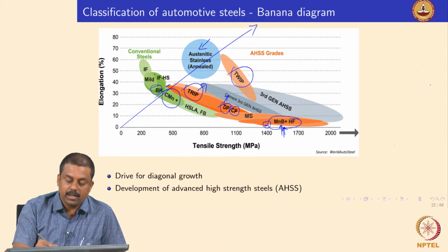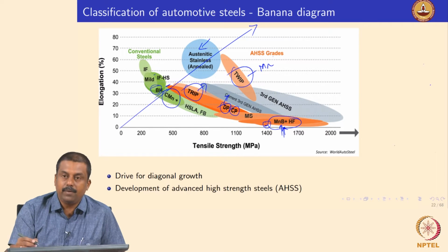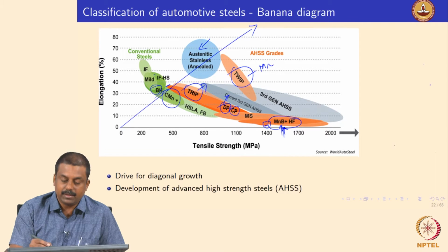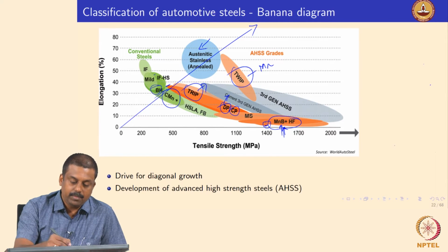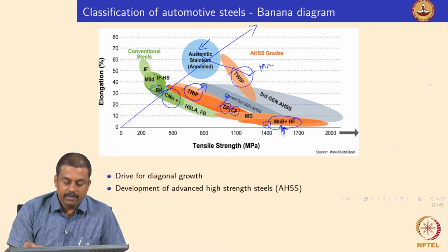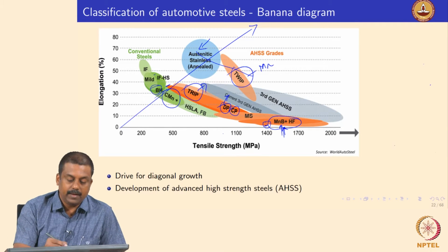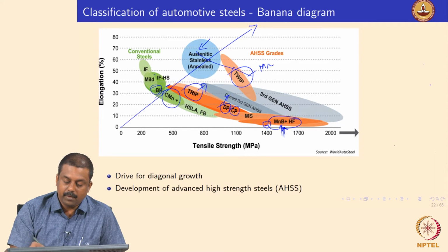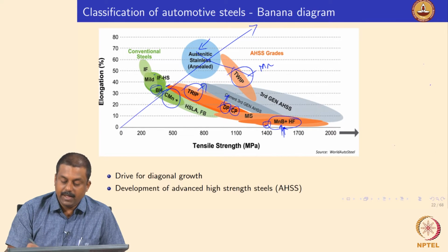These steels also contain a high amount of manganese in order to form a twinned microstructure, and the weldability of this steel is still considered very poor if you use the conventional welding processes. So we will also not be looking at these two steels. We will look at in subsequent classes the physical metallurgy of these first and second generation advanced AHSS steels, and the hot forming and complete martensitic steels which have very high strength upon forming.